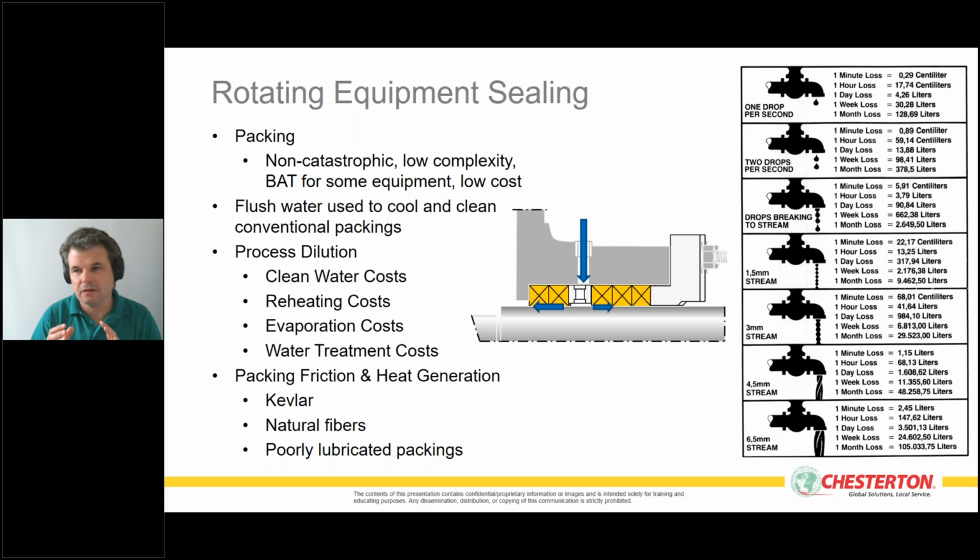But when packings are commonly used without paying too much attention, a lot of times flush water is used to cool and to clean the conventional packing. So what you will see is that clean water is injected to keep the surface between the packing and the shaft clean, so it doesn't wear too much. So this water is doing a number of things.